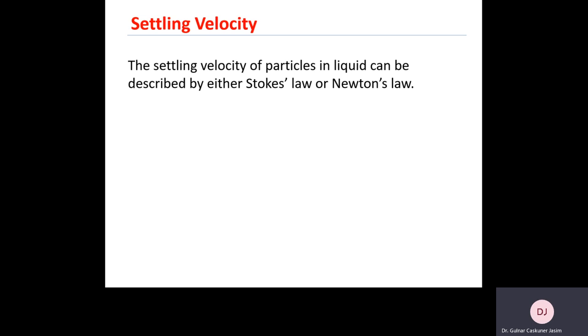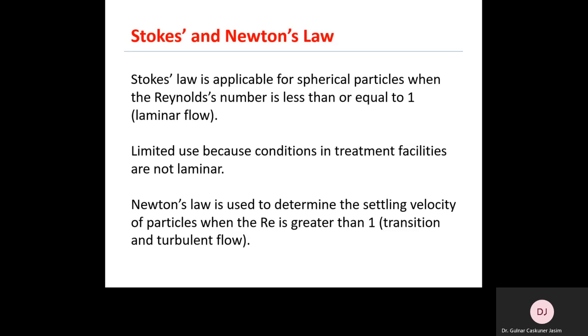The settling velocity of particles in liquid can be described by either Stokes' law or Newton's law. Stokes' law is applicable for spherical particles when the Reynolds number is less than or equal to 1, which shows laminar flow.